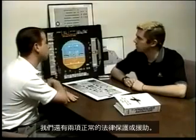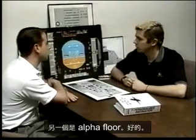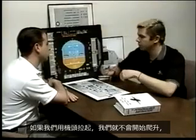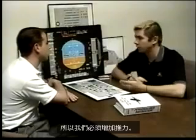Yeah, in normal law we've got 2 more protections, or aids. One is a low energy warning. The other is alpha floor. Okay, describe the low energy warning for me. All right, low energy warning. We're going to hear it, and that's all you're going to do, you're going to hear it, and it's going to say speed, speed, speed. That indicates that the only way to get a positive flight path angle is by adding thrust. If we pull up with our nose, we're not going to start climbing, so we have to add thrust.